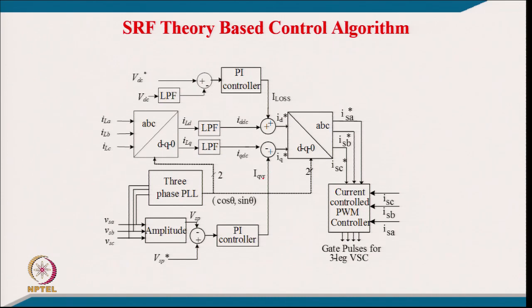This is to be generated by the D-STATCOM minus the reactive power required by the load, which it meets locally. The difference will flow into the supply, and we have ID and IQ of the supply, and then we use the DQ to ABC transformation. So, we get the 3-phase reference current on the grid side, and we sense the grid current, and we have a current controller to generate the gating signals for the 3-phase voltage source converter operating as the D-STATCOM. So, that is the block of the synchronous reference frame theory. It is also called DQ theory.